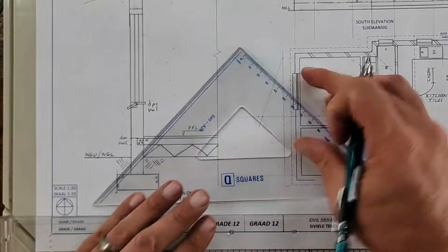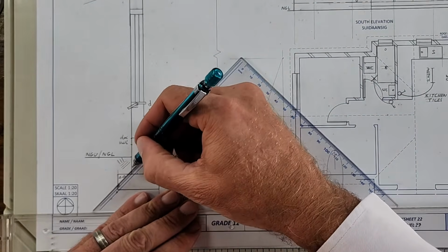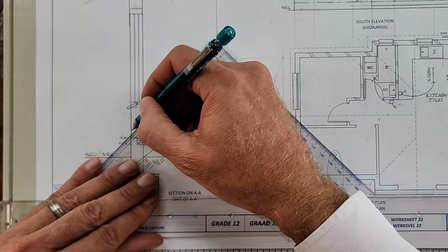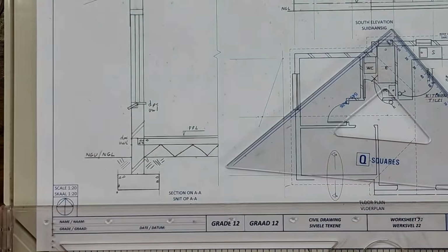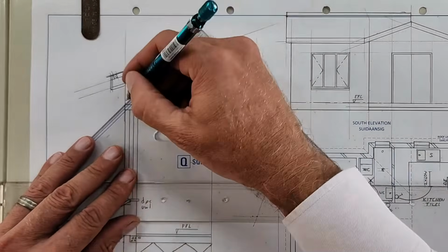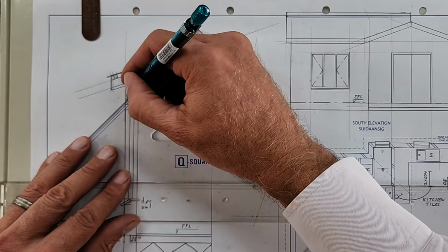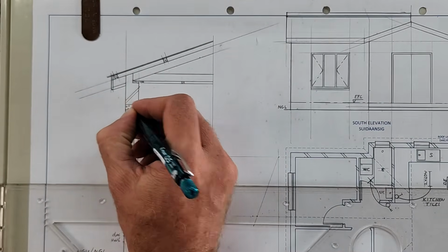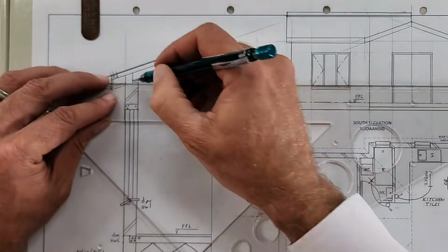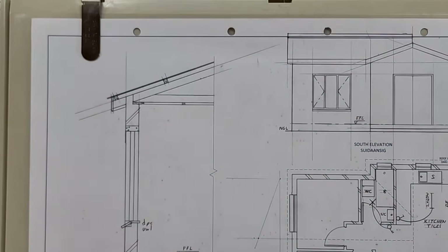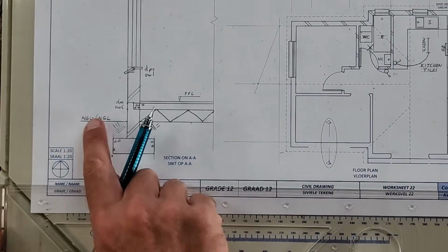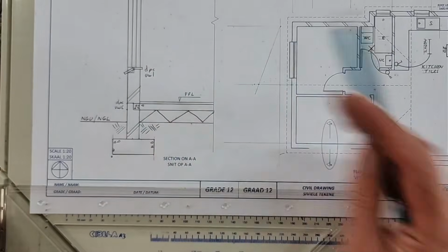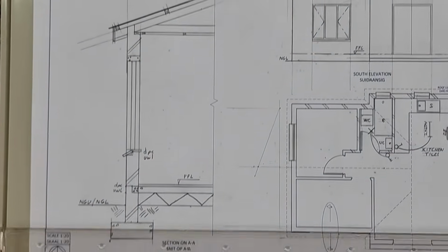Then you have to hatch it. 45 degrees. Again, every part needs to have that 45, so don't make your spacing too big. It's not 30 degrees, it's not anything else but 45 degrees. What's missing? One last thing, what's missing? Help me out. We have a lintel here. Right here, so if I look at that from the bottom, foundation, natural ground level, compacted fill, we've got the damp proof course, finished floor level, details here, done and dusted, moving up.